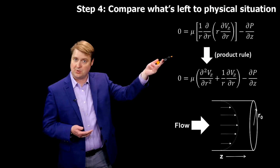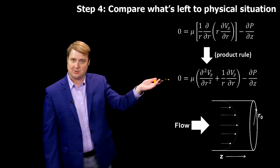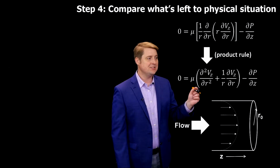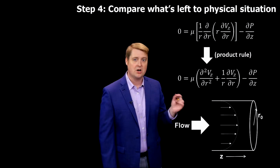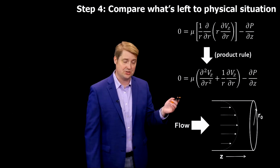Let's break it down. There's the product rule that we have to remember from calculus, so make sure that you review that if this looks confusing to you. Once we apply the product rule, we're able to get this expression. So what do we have here? Well, we've got this first term. This is the second derivative of velocity in the z direction as a function of r. What it's basically saying is, is there a curve to the velocity in the z direction? That trend is a function of r.